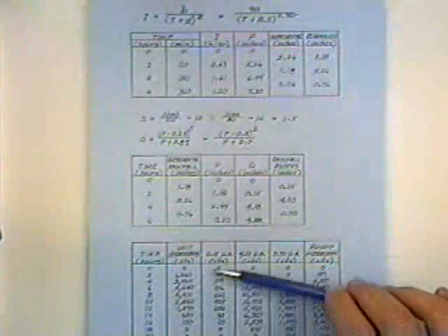On the last example you just did, you have the 3 columns with the 0.15 and the 4.03 and the 0.7. What do we multiply? I don't see where those numbers are coming from underneath it. The numbers that you just cited, those are direct runoff volumes corresponding to time increments of rainfall. In the previous example, we developed a unit hydrograph. So we took the unit hydrograph, and we multiplied the unit hydrograph ordinates by those numbers. And then we added them all together.